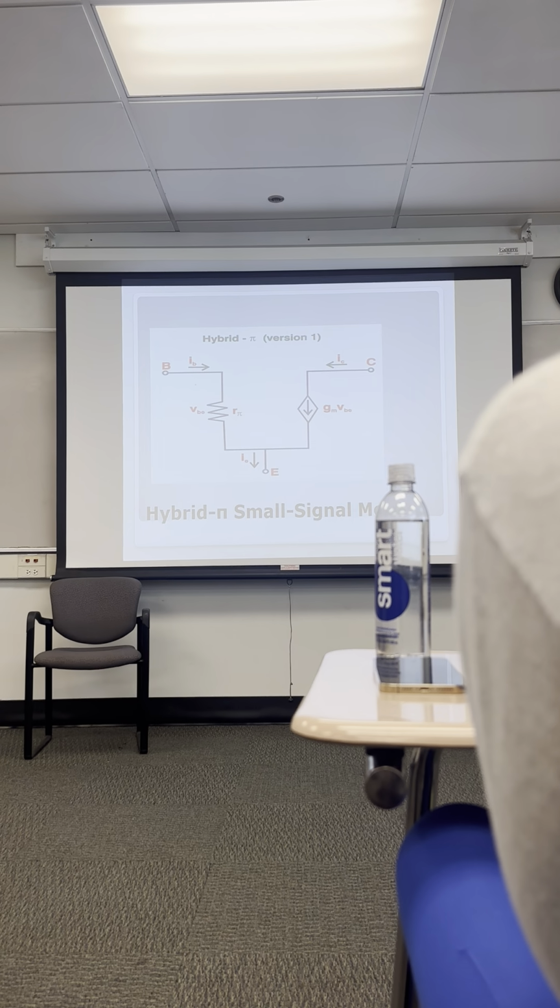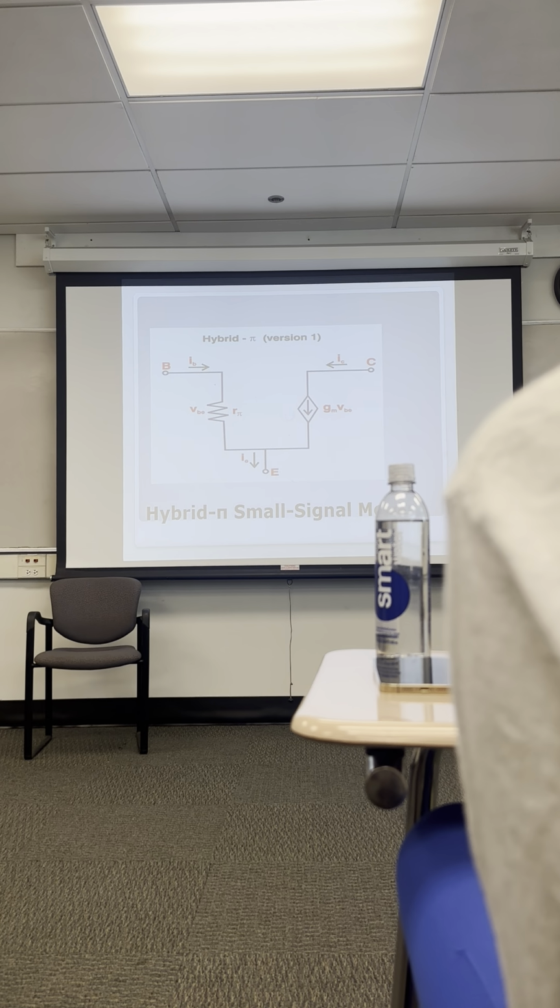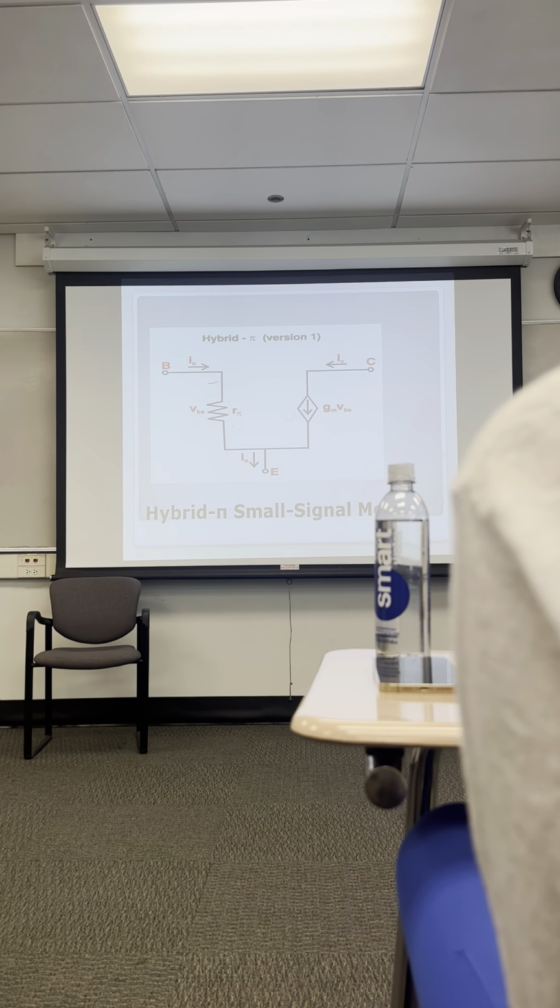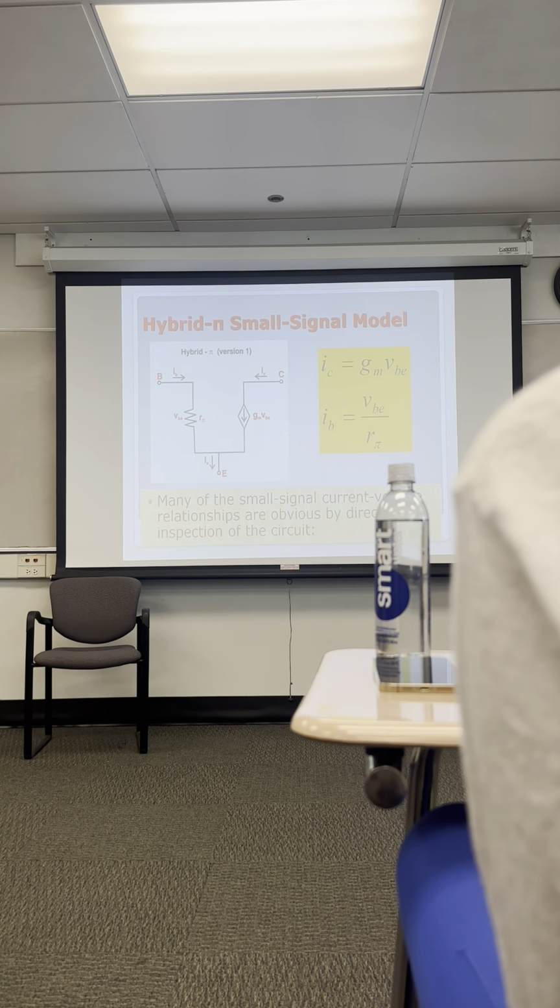We basically developed what's called a small signal model. This is the simplest, a hybrid pi, probably level 1 model for an NPN transistor. So we have an R pi term, and we have G sub M times the base-emitter voltage. Here's the emitter current going in, the base current is here, and the collector current. And we note KCL is valid for this symbol.